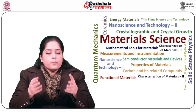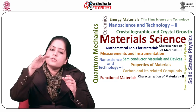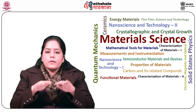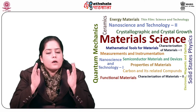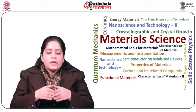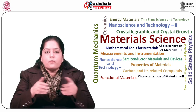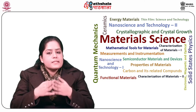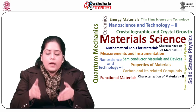Stacked transistor approach. Now stack a p-channel device on the top of the n-channel device. The two can share a common gate electrode. This structure can result in a very dense static and dynamic RAM cells because it eliminates the conventional device isolation problems. So a pair of these devices forms a static memory cell that resembles the static RAM.